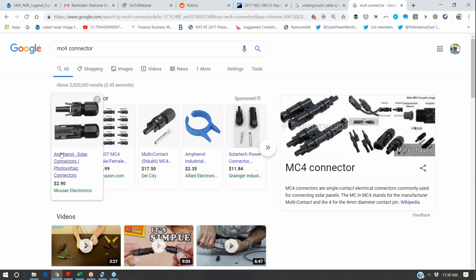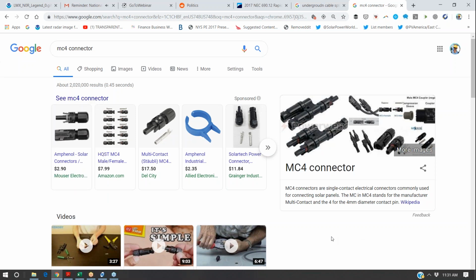One example would be the module to module connection on the rooftop, where you're just plugging the module into the next door neighbor. That's not inside of conduit. And so we have a splice box. I guess you could say that maybe the housing of this is the conduit body, but it's solar specific. It's a way that you can splice or connect two solar modules together, or the end of your solar circuit to your home run, without going into conduit or a box to perform that splice.